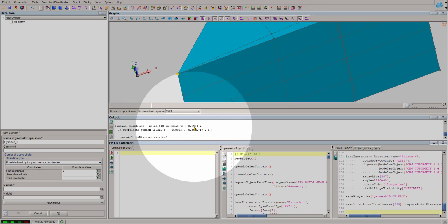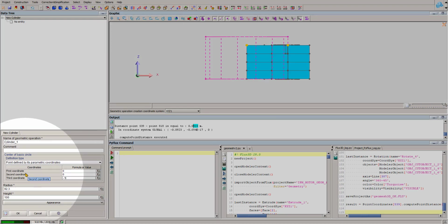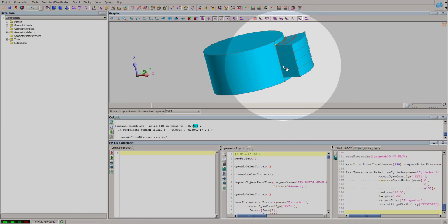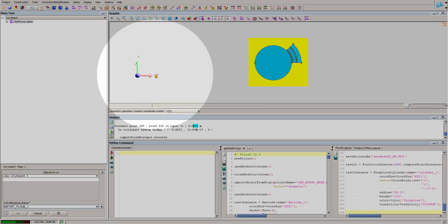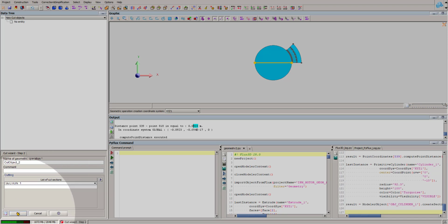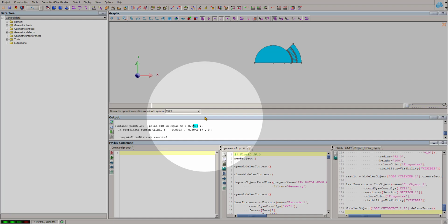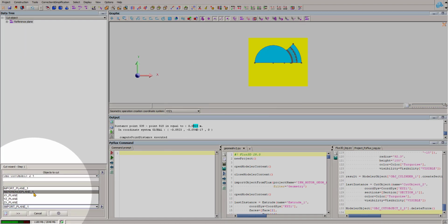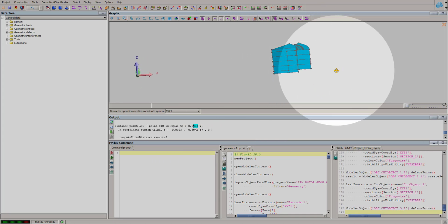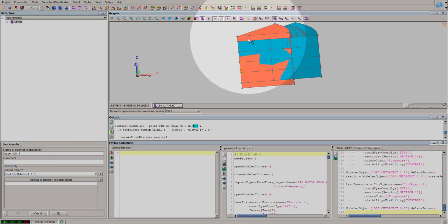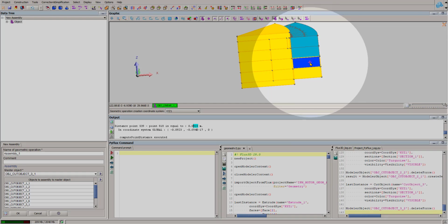So I am measuring the diameter or the radius of the sliding cylinder of the rotor. And I'm going to use a height of 100 millimeters and center the cylinder around the rotor. Then I will cut the cylinder according to the reference plane corresponding to the portion I want to study. Then I am going to make an assembly between this cylinder portion and all the layers of the rotor.